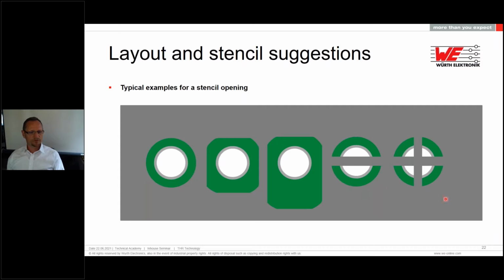And now number 4 and going to number 5, those are the opposite direction if you have to reduce the amount. Yeah? And especially number 5 is mostly used when both sides are printed with solder paste to achieve a desired soldering result.